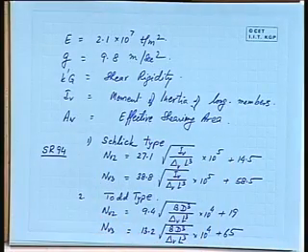Now, one thing is very important, that as the shape takes place, when we are talking about a particular mode, 2-noded mode or 3-noded mode, in a particular mode, the added mass is of a different quantity, and the effect you will find that the frequencies will keep on changing.